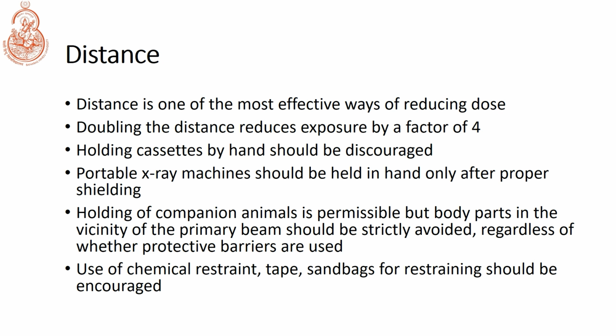The next is that holding of the cassettes by hand shall be discouraged as much as possible. Always plan to have a cassette holder to hold the cassette, and avoid direct handling of the cassettes using the hands. The portable X-ray machines should be held in hand only after proper shielding.